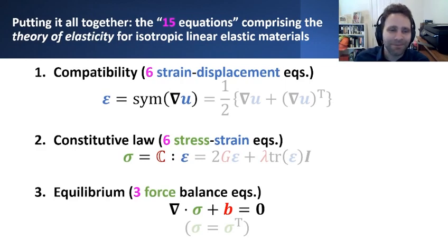And then finally we came up with these equations governing equilibrium, which basically provided a statement of force equilibrium in a point-wise sense throughout the entire body that we were looking at. And these equilibrium equations, for which we provided several alternative derivations, led to these governing differential equations expressed in terms of this stress divergence term plus whatever extra body forces, which had to all sum up to be equal to the zero vector, and that had to be true, again, at every single point in the domain.